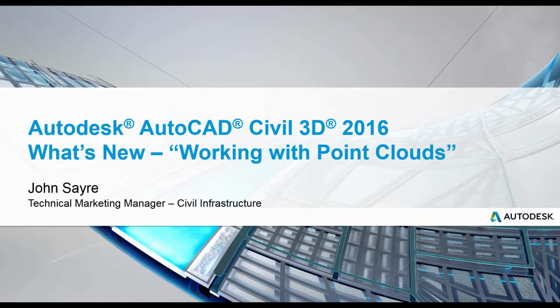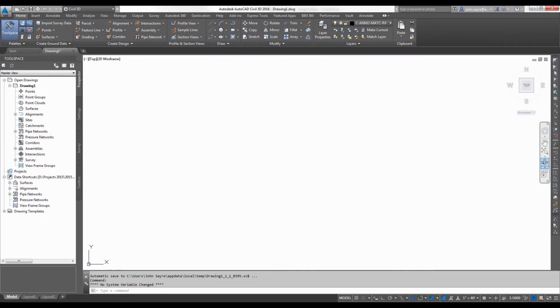Today I'd like to talk to you about one of the What's New features in AutoCAD Civil 3D 2016, working with point clouds. When using AutoCAD Civil 3D 2016, you can also take advantage of newer enhanced tools in AutoCAD 2016. When working with point clouds, you will see product enhancements such as point cloud object snaps, point cloud crop states, and an addition to the point cloud manager that displays the on-off buttons for scans and regions that you would be applying inside of Recap. This gives the user more functionality to visually display and use the point cloud data. So let's take a look.